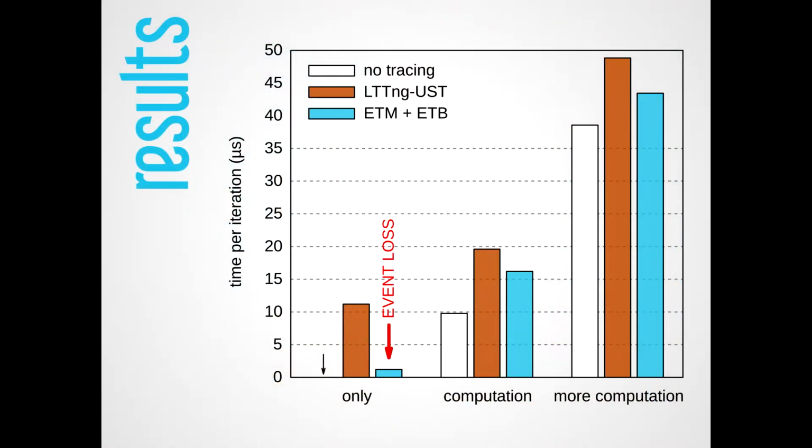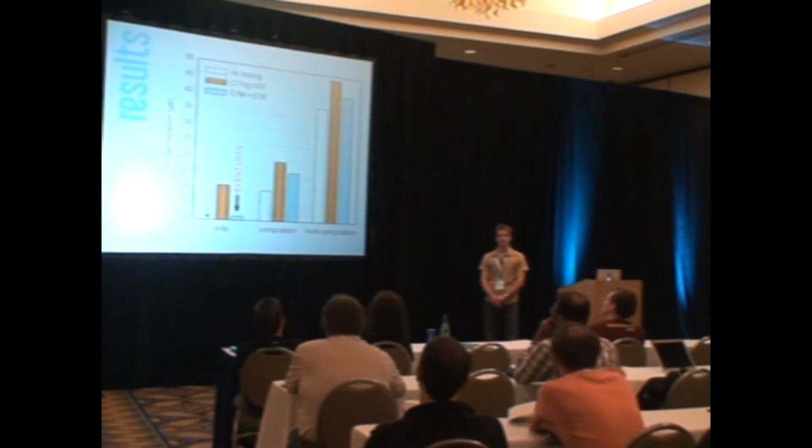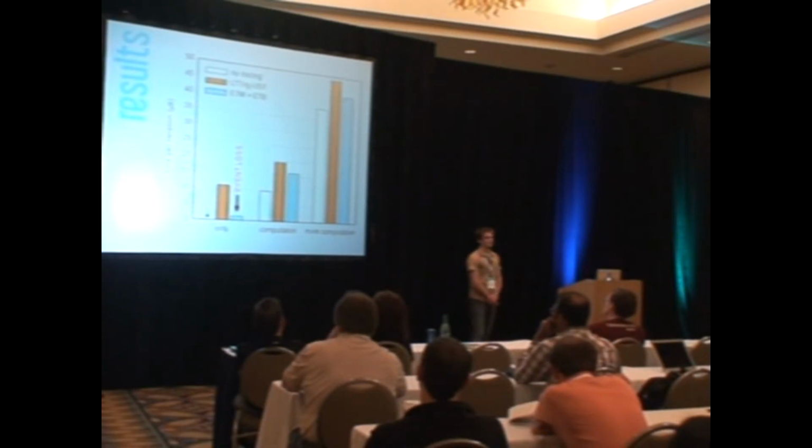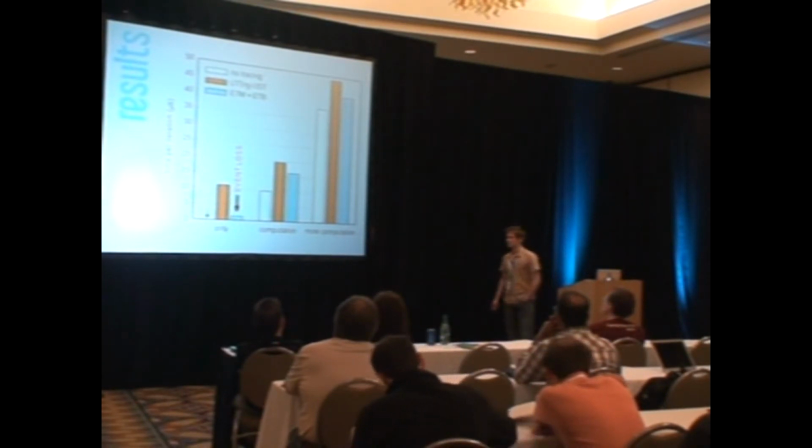It's the same representation as with STM. You see a program traced with LTTng and another one traced with hardware using ETM and ETB. And you can see that there is an improvement. It can be faster with hardware. The problem is that with ETM, there is a limited number of trace points, since ETM has only a few address comparators, so you can define a limited number of points or events in your application. On the platform I had, it was three address comparators, so only 3 trace points. The other problem is that you cannot embed payload in your event, because it is not meant to.